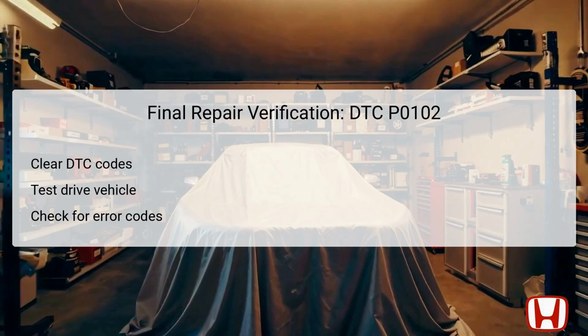Monitor the conditions that previously triggered the code to assure they do not reappear. After the drive, check again for any error codes in the system. If no codes are present, this indicates that repairs have effectively addressed the issue. This step is crucial for ensuring that vehicle operations return to normal with improved performance.